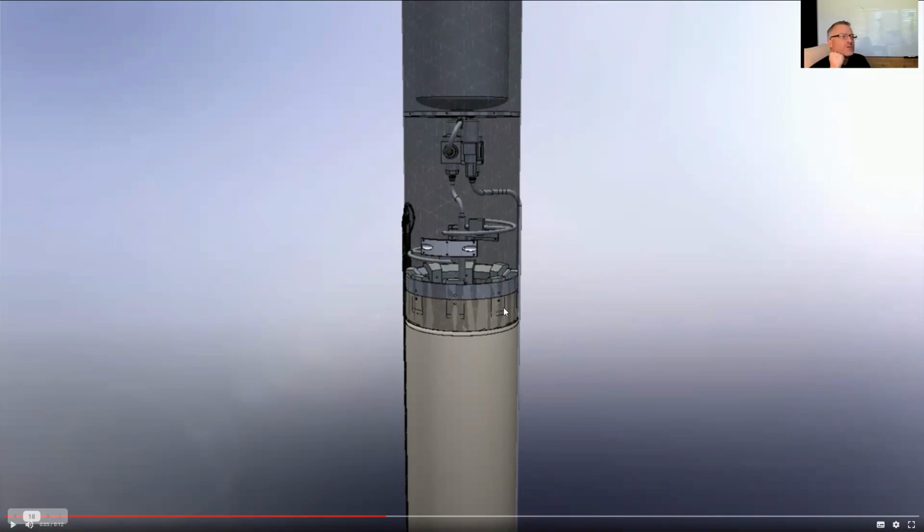Just a question. You alluded to pumps. Why carry another tank of compressed gas as opposed to actually pumping fuel and oxidizer into the engine? It's all about mass savings and simplicity. If you can design a pump assembly that is lighter than an equivalent tank and pressure regulation system, then it is obviously more in your favor to go with the pump system.